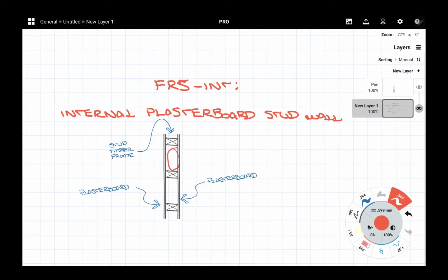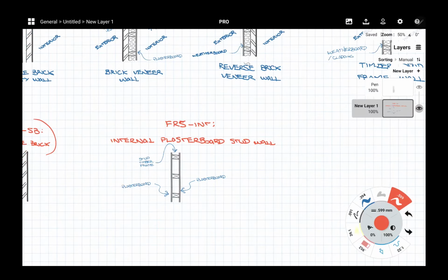That is not done very frequently, as far as I know, because typically that insulative role is given to the external walls, where that transition point between the external and the internal environments is, whereas these guys here are just separating the rooms. With that being said, sometimes internal walls can play structural roles in a building, and so they will be bigger and more robust, and they may not be one of these true types that I'm showing here.